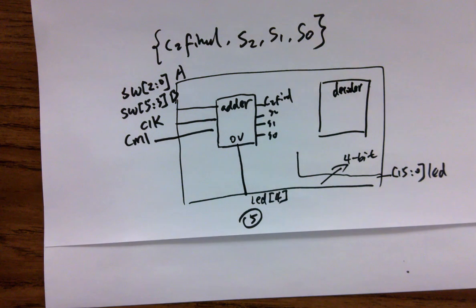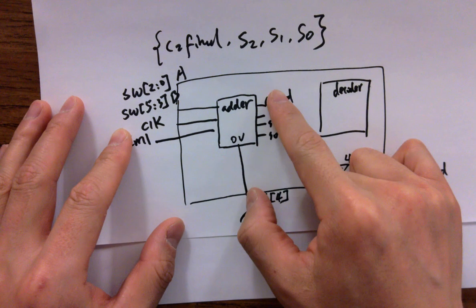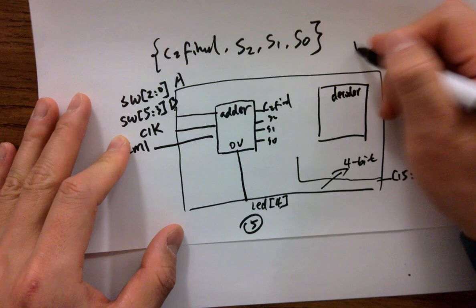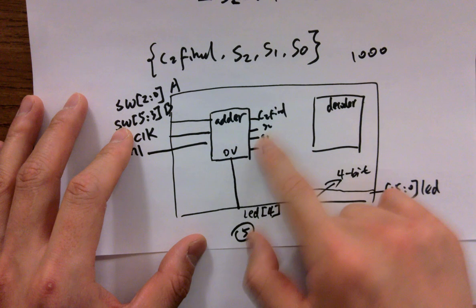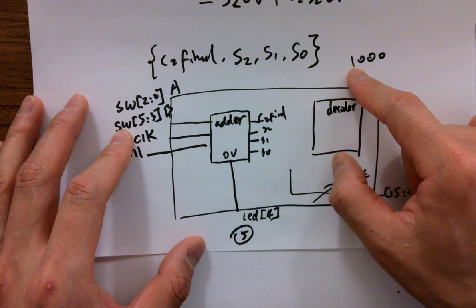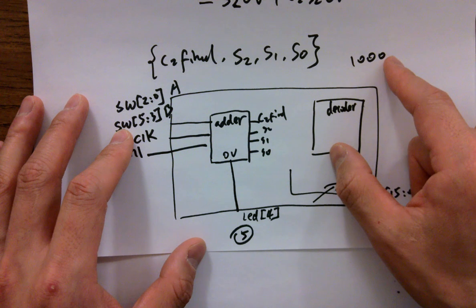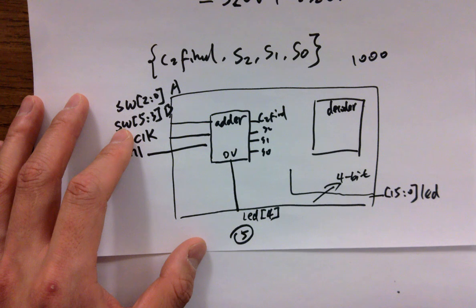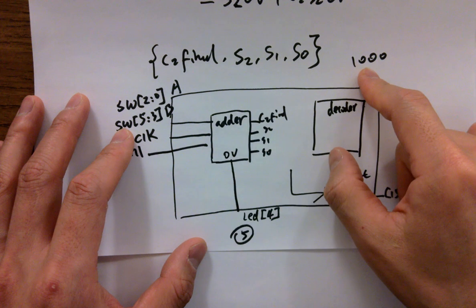This decoder could be different because in the previous labs, it was unsigned, right? If you receive a 1, you have to change the numbers in the lookup table. Previously your decoder receives this number, unsigned. You are trying to give a pattern of the 7-segment display as 8. It's basically turning on every single LED, all zeros, right? But now it becomes different because whenever you are receiving this, you need to display a what?